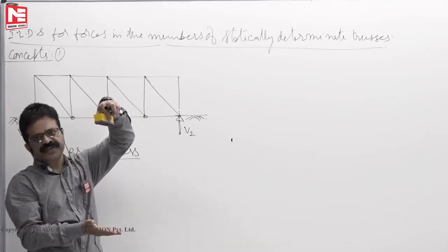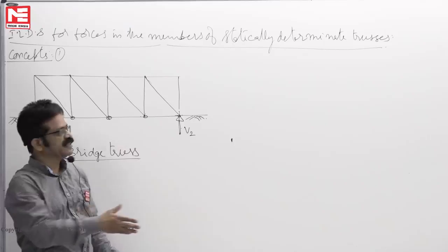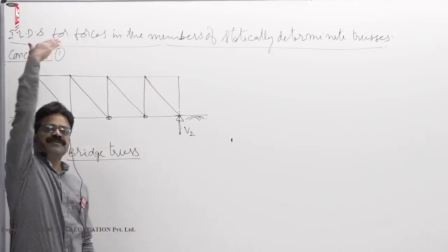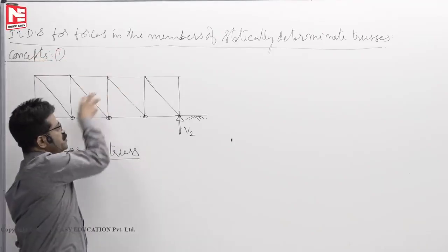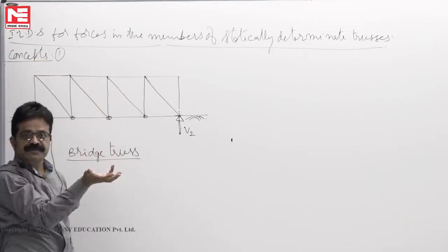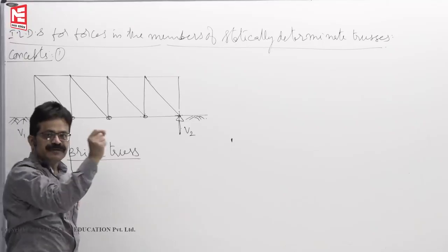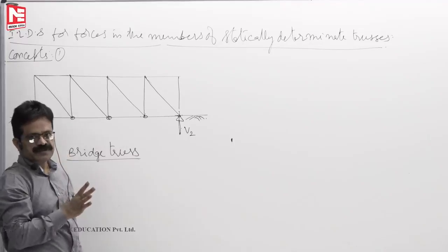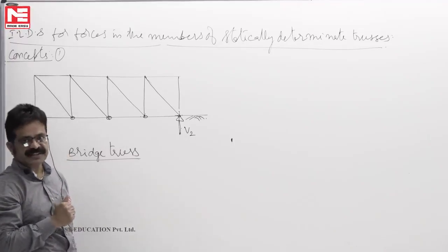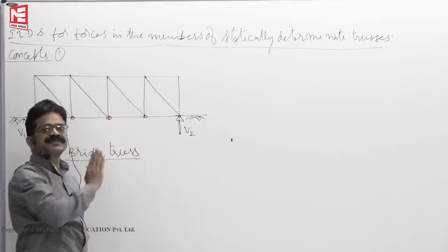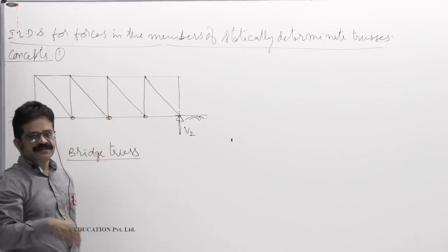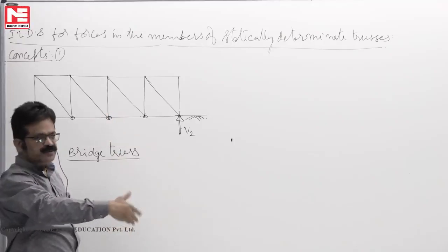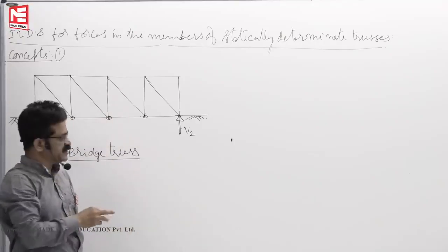Solid rectangular section, if you have 600 mm or 60 centimeters, you can have here 4 meters also. So you can increase the depth of the beam to 4 meters, everywhere holes. Then weight of the beam is less. Individual members are subjected to axial forces only and resist the shear force, which we want to call panel shear, because beam shear is now transferred as panel shear. So that's how for larger spans without any intermediate columns, we can go for truss bridges.